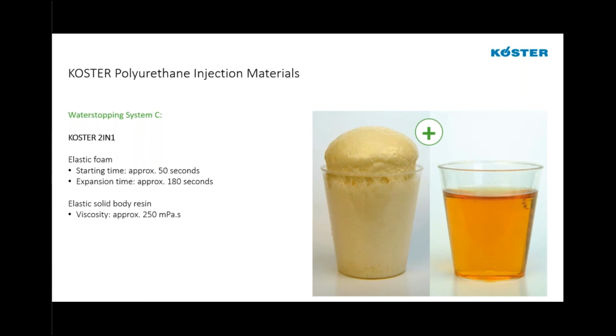injections. Also, it has an extended pot life, about 45 to 50 minutes, so you can inject the material without having to clean the pump and inject again, depending on the size of the crack, obviously, and the size of the injection scope. But the 2-in-1 is like your all-purpose for any kind of water-bearing crack.